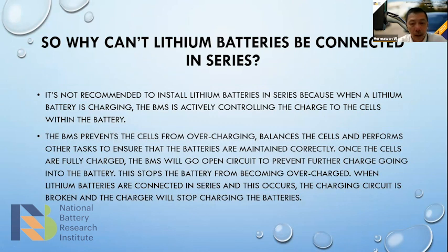The problem in the pack of the battery in series is that they have a pack protection, and the pack protection will stop if it finds one of the cells is over or lower than the protection number. And then if you series the pack, if one pack stops, it means the whole connection will be open. Sometimes we don't want that. This must be carefully understood.